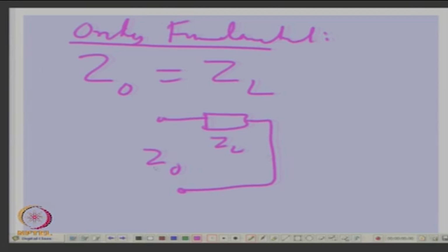So, what we have noticed is that with space harmonic fields, the impedances to positive, negative and zero sequence will include, apart from the fundamental impedance, the impedance due to those harmonics, but not all harmonics will be there at all sequences. Particular harmonics are there and some harmonics vanish. If you have single phase, there will be certain fields. If it is 3 phase, certain fields will go. Okay.